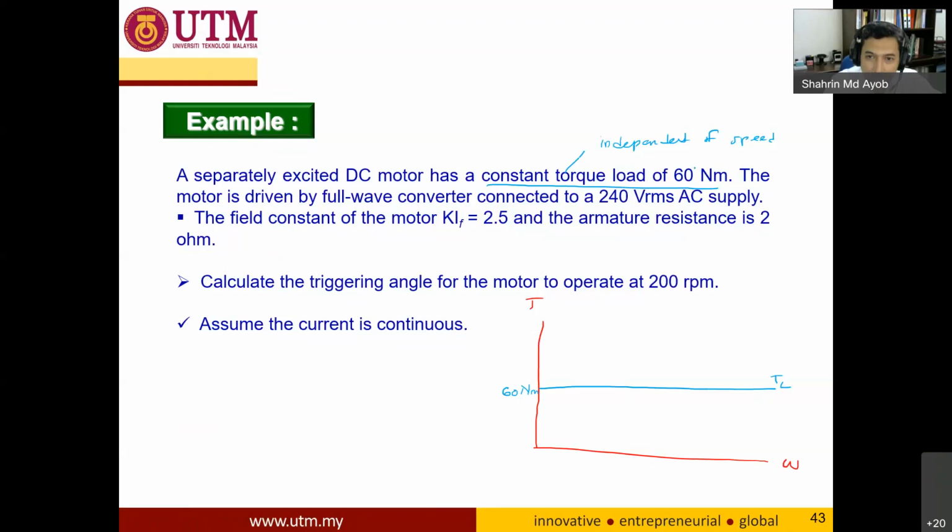Okay, and then this load is connected to the DC motor. I'll use black color. So you have this torque-speed characteristic of your motor, which should be a straight line. This one is your motor. This one should be the no load speed, and this one is your starting torque, where your speed is 0 RPM. This axis is RPM.